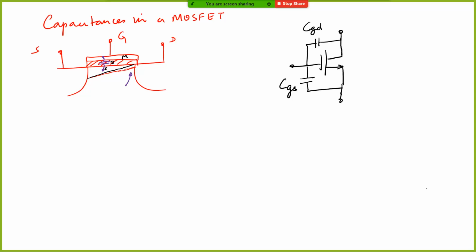The origin of the capacitor is that it is a normal parallel plate capacitor, and in fact CGS and CGD are both proportional to the area, which is given by the product of the width and the length. Now, where else can we have capacitors?